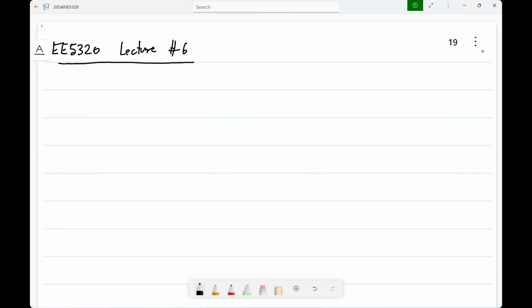We were discussing component variations. That is, you expect the component parameters like resistivity, sheet resistance, or threshold voltage to have some values, but they will not have those exact values. There will be changes. So, like I said, there are process variations which are related to the foundry and when it is fabricated and so on. And every run there will be something. And then there are variations across temperature, and semiconductor properties are especially sensitive to this. Resistivity also could be sensitive, capacitance not so much, and so on.